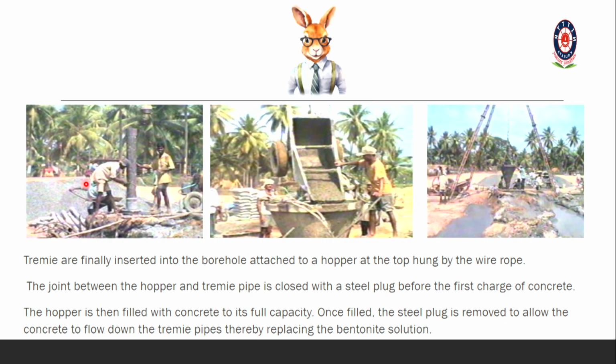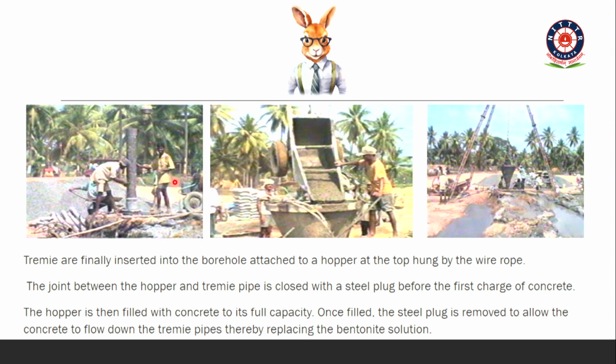Then after lowering the reinforcement, you will be using the tremie method of concrete to do the concreting. You can see you are fixing the tremie pipe, then you are pouring the concrete. By using this, automatically the vibration will be done and the concrete will settle systematically in the pile. And also this is the indirect way of identifying: once the pile is constructed at the required depth without any seepage, then the concrete overflow will take place.